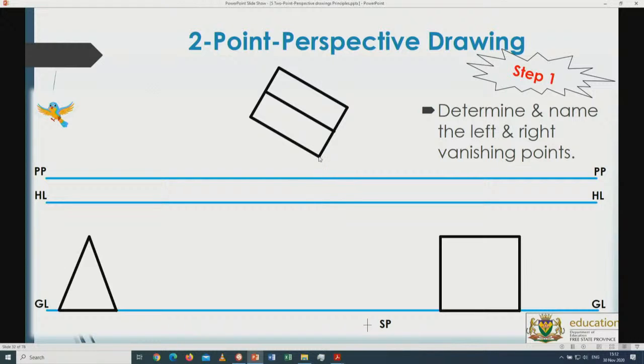It stands some distance away, so I can't use this point, drop it downwards and say my view will start over here. I have to extend it, go downwards on it, find the height of it, go to the left vanishing point, and somewhere on that line I will be able to find that point. More of that just now. First of all, vanishing points, parallel to the side, left vanishing point to the picture plane, go downwards until you get the horizontal point. Right vanishing point, go downwards until you get the horizontal point, which is that one. Right vanishing point, left vanishing point.